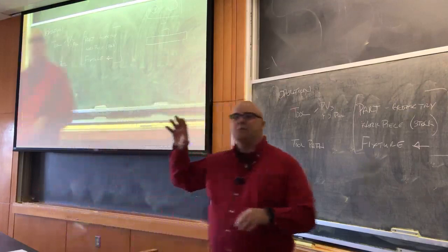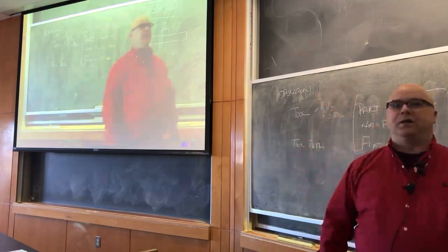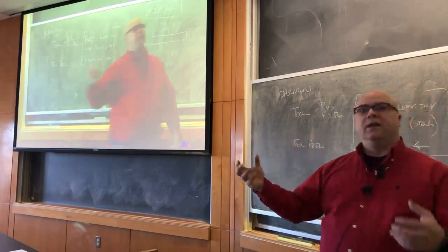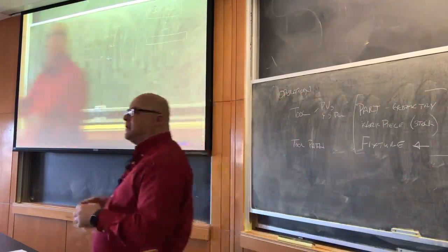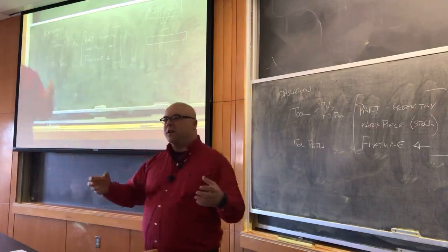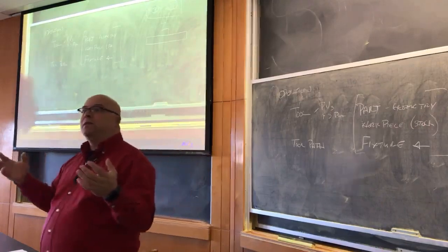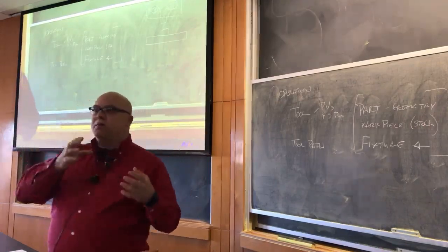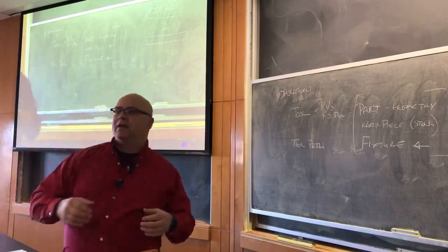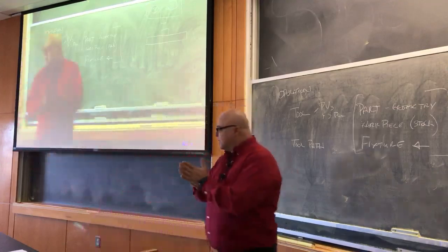The other reason we do that is because you think you're only going to make this part once. But you're going to make it for your MQP, let's say. You're going to install it into the assembly where it goes. And then you're going to realize, I need to make this little change to make the thing work better. And then you're going to go back and make almost exactly the same part, or maybe even the same part, maybe just broke it. And if you edited the code manually on the controller, you're going to have to remember what all those edits were, and you're going to have to do it again. If you just fixed it in the CAM software, then it's just fixed. So that's the other reason we do that.